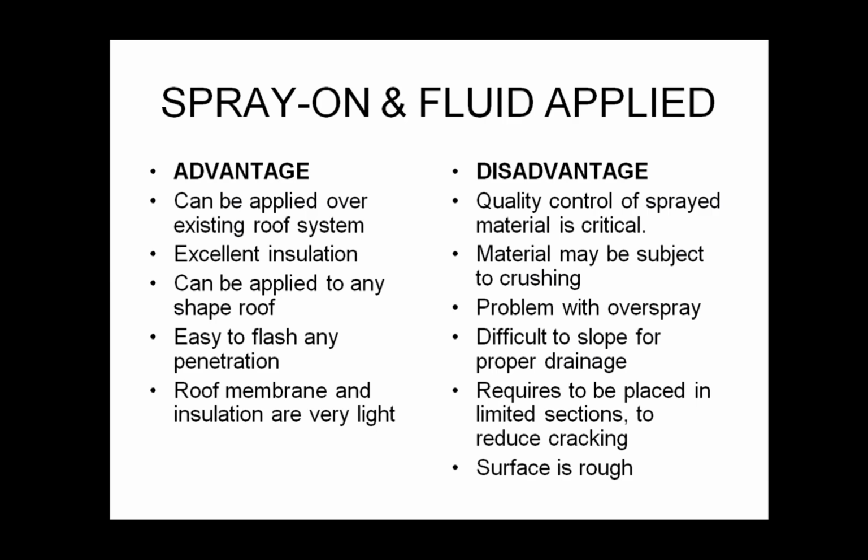Now, the disadvantages are, you kind of have to trust that the mix is correct and try to test it while the materials are going in and sprayed. We do a lot of testing sometimes after it's done, but after it's done, the material's already in place. So if it wasn't mixed correctly and sprayed, it's really difficult to pull this stuff up and redo it. And that's the same for any application of a spray-on or fluid-applied coating, including waterproofing for roadways, highways, buildings, you name it. So quality control is always the toughest thing to get here.